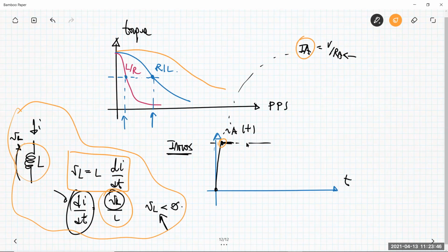And this leads to the fact that T double star, the turn off time for the circuit which has the diodes, is larger than T star, which is the turn off time for the circuit which doesn't have any freewheeling diode.